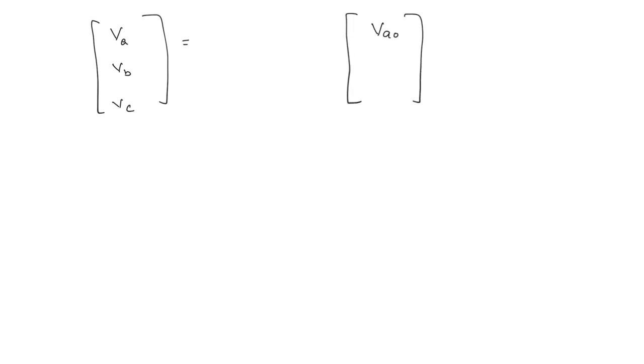Here let me tell you one point which might cause a confusion, because in different books it is written in different ways. Okay. So what we took here, we took the original phasors VA, VB and VC, and what we did, we expressed this in terms of, first we are writing the zero sequence component, remember. Next we are writing the positive sequence, and next finally we are writing the negative sequence, right? And here the A matrix, then it is going to be what? 1, 1 and 1. In the second row it is going to be 1 alpha square and alpha, and finally 1 alpha and alpha square.